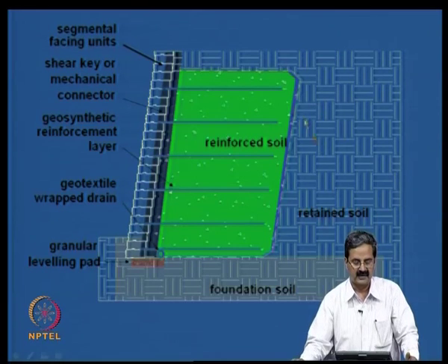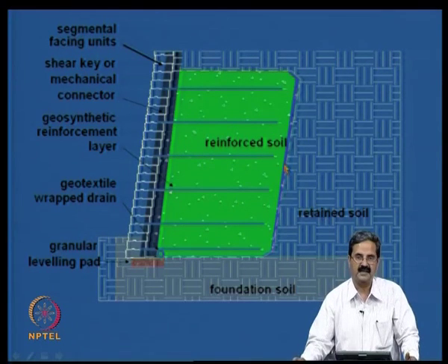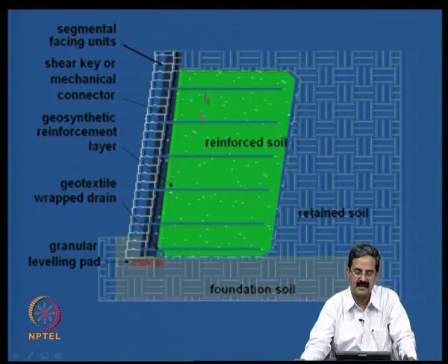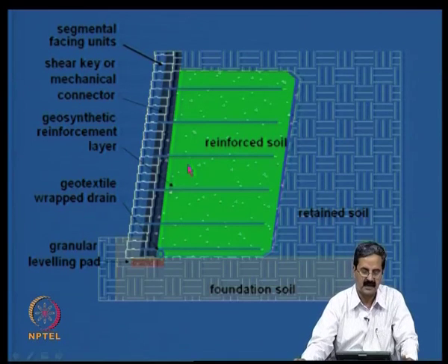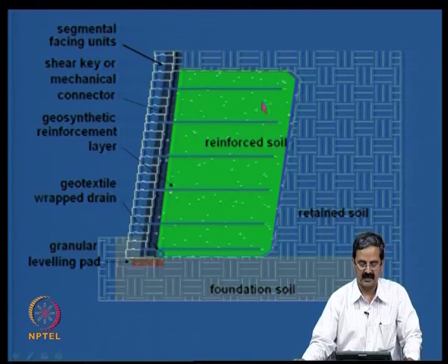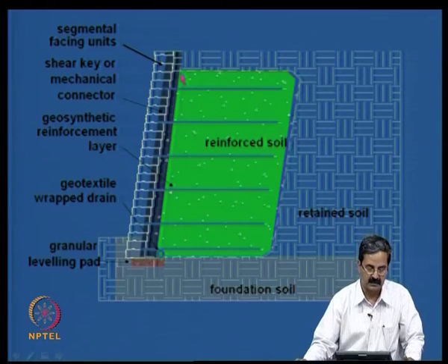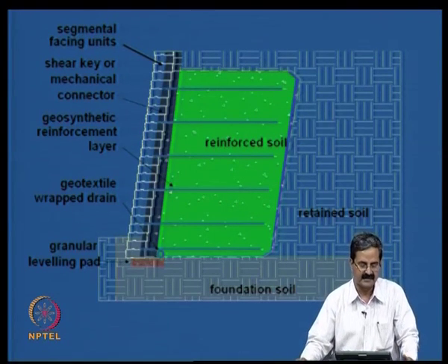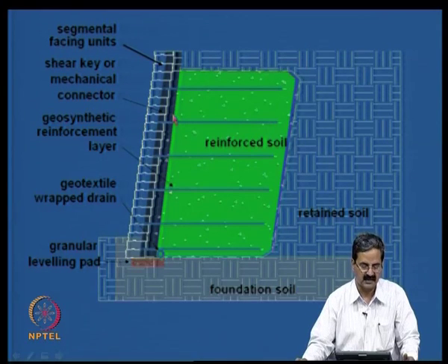As mentioned earlier, the reinforcement elements are designed to take care of the lateral pressures. Once you know the length and the spacing, as we have seen in reinforced soil slopes, and you know this design comfortably, then the pressures on the facing are going to be minimum, and we try to provide some sort of segmental facing types. It can be full facing, or even concrete panels, which we see in most of the flyover projects in India.